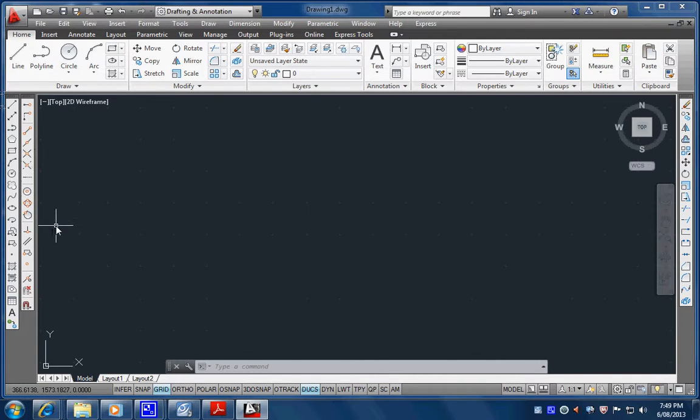So this is one of the things that actually sets AutoCAD apart from other software, like let's go as low as Paint, for example, that comes with Windows. And the other difference between Paint and the CAD software is that one is vector-based, the other one is pixel-based. So when I draw a line, I'll just click this, for example, and then I click here with the left mouse button, and I lift my finger off it. I don't hold it and drag it. Then I come up here and I click it again. I get a line. So all you remember is those two points that I've clicked, whereas a pixel image will have a million pixels between the first point and the last point.